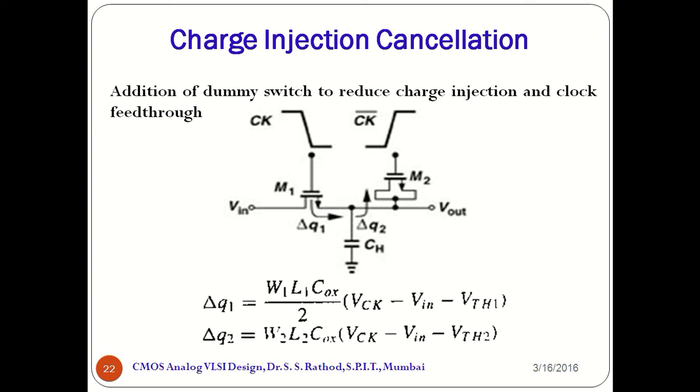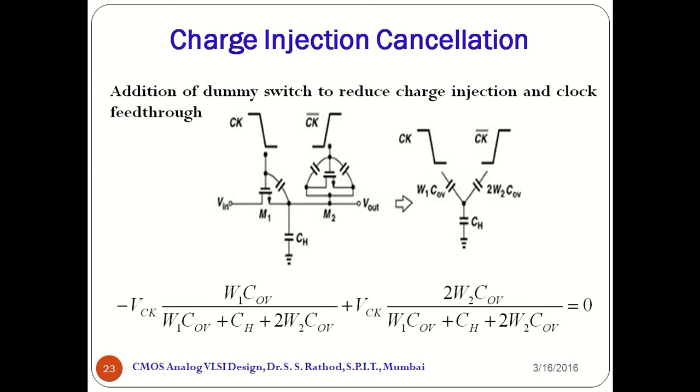However, unfortunately, the assumption that we have considered of equal splitting of the charges between source and drain is generally invalid, and that makes this approach less attractive. However, there's one more interesting thing: if we choose W2 equal to 0.5 times W1 and L2 equal to L1, then the effect of clock feedthrough is by default suppressed.